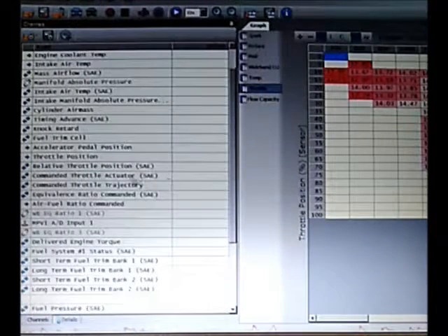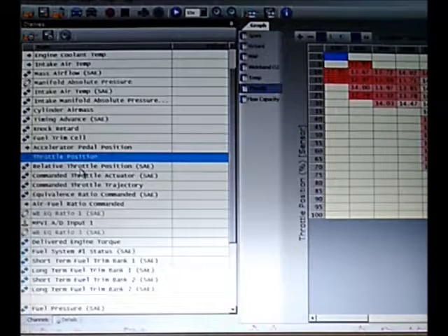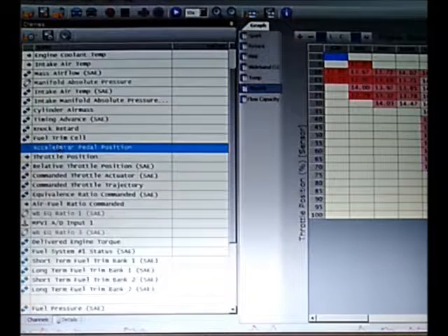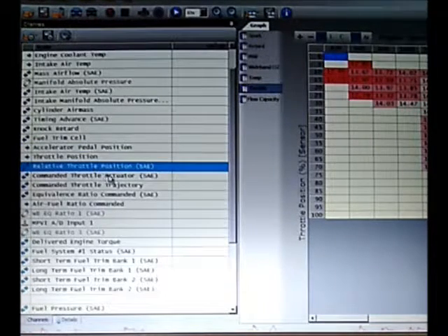And then you can pick what type of throttle you want. So in addition to the accelerator pedal position, you just want a throttle value that's going to tell you what the actual plate angle is, or the plate angle percentage. It's got to be a percentage. That way you can correlate that back to your accelerator pedal and find out at what pedal position it is actually making a change in your throttle plate position.